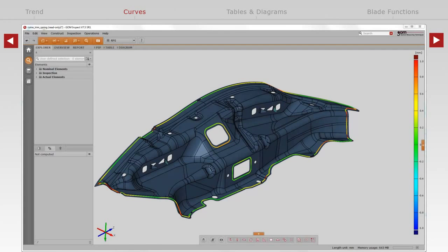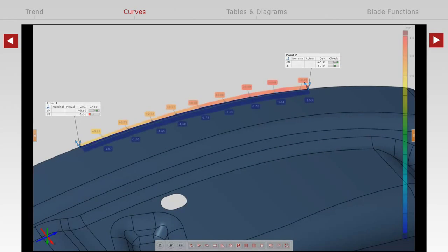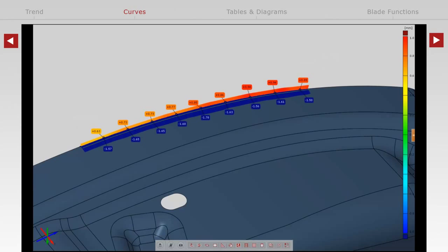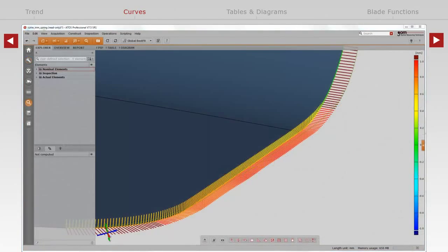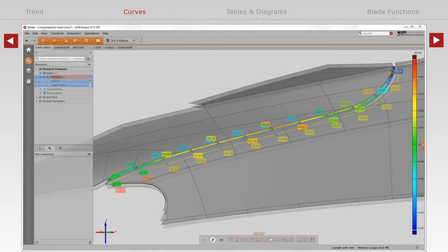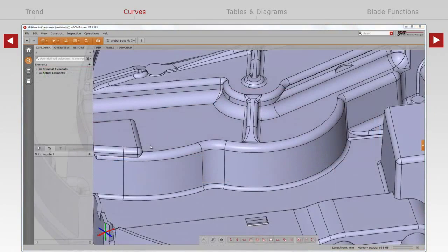Curves is a concept that completes the idea of full field inspection data. Rather than having point-wise information, such as the trim and spring on the sheet metal, GOM introduced the idea of having the data also in between. The applications reach from radii analysis over trim and spring up to flush and gap analysis for inspection, and contrast line and tapes for reverse engineering. Let me demonstrate this with the following example.